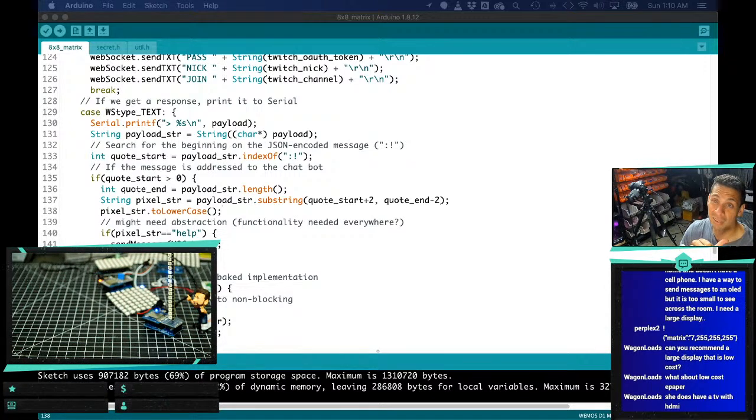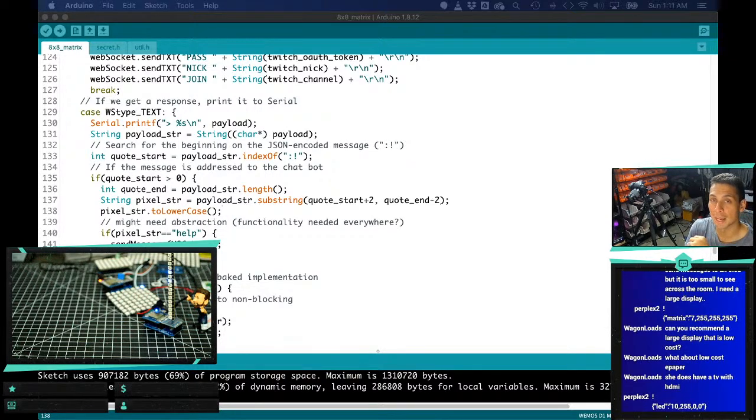TFT is the other technology. You can find TFT displays that are fairly big, again 5, 7, even 10 inches. It just gets a little hairy with the drivers that can be driven by something like an ESP8266. But not OLED. Once you get to those sizes, you want to do TFT or LCD.